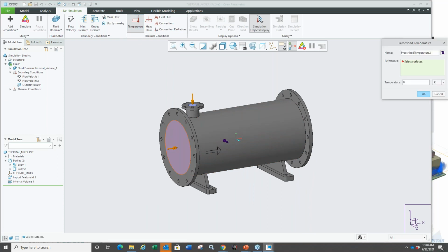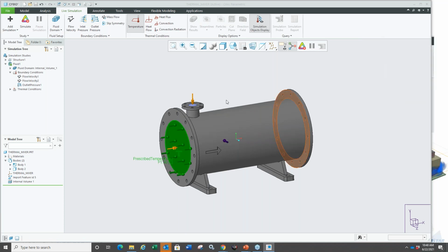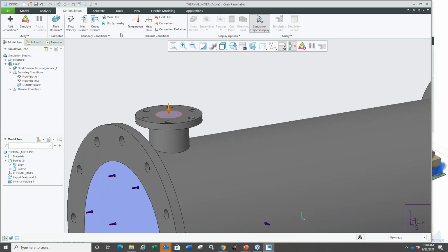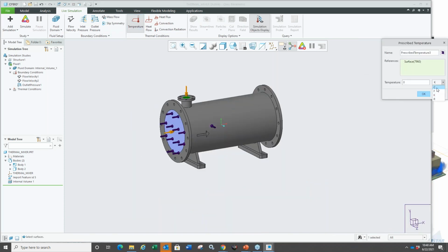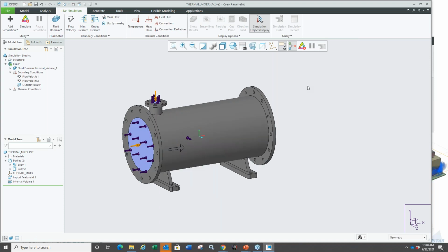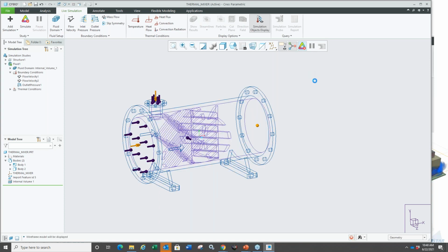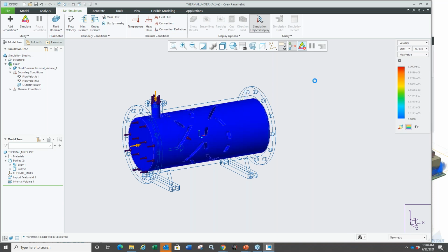I could say this has got to be about 40 degrees C here, and we'll set this one also with a temperature of, let's see, we'll make it hot here, 120. And that's pretty much it, right? Again, there's no run button or anything in here. I'm just saying, let's view. And it's essentially going to give me results immediately. That is pretty quick for a fluid problem, right?